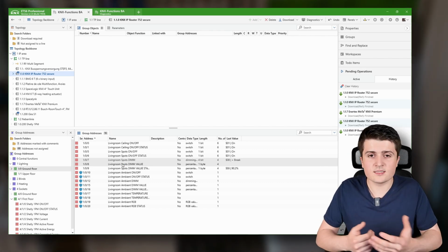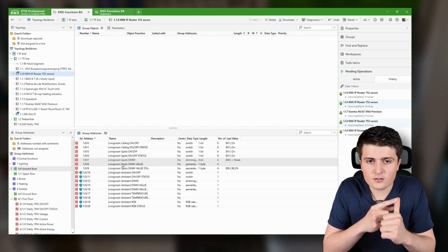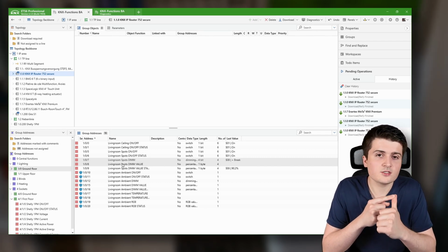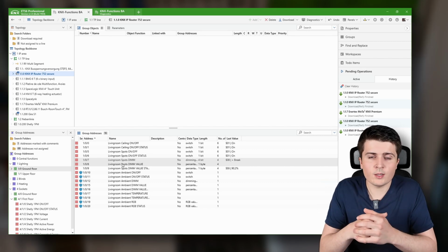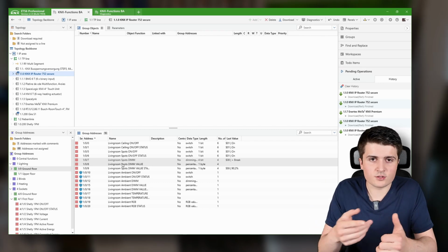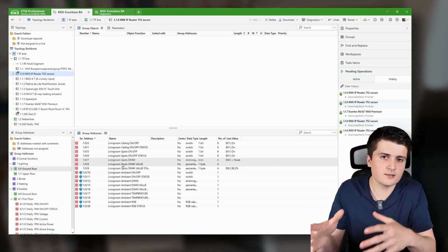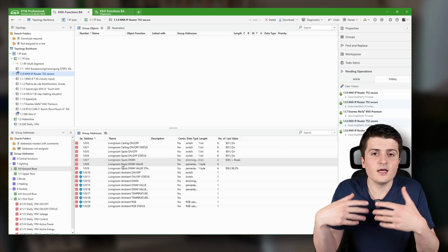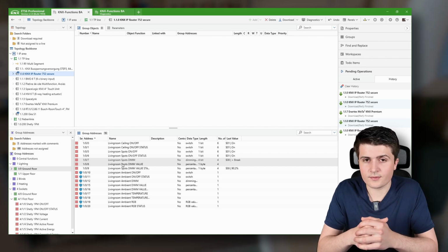So to quickly summarize what you need to know. First of all, the Shelly device is not a certified KNX device, and so therefore you also don't parameterize it via the EDS. So what you need to do is that you need to go into the web interface of your Shelly device and configure KNX there. So first of all, the physical address. Remember, here we need a physical address that sits on the IP area. And then we need to set up the group addresses.